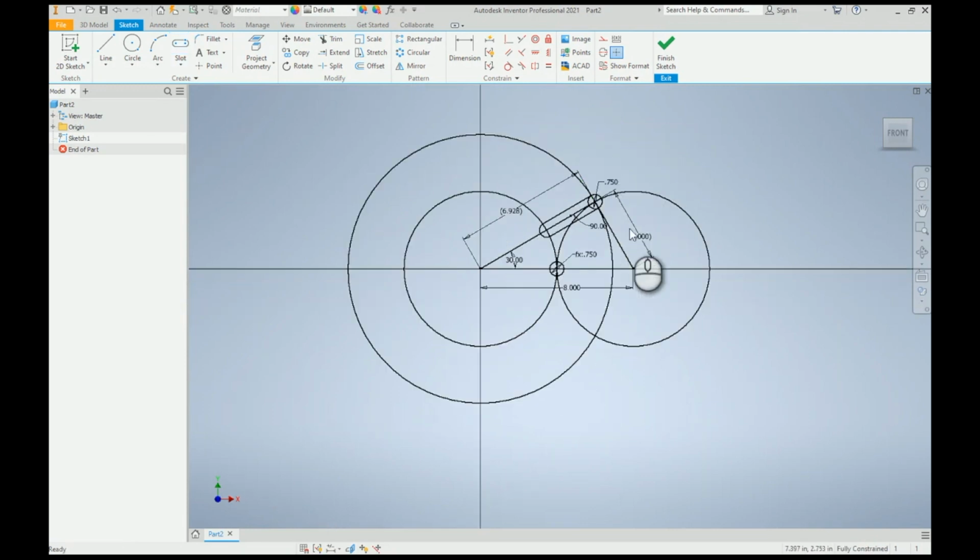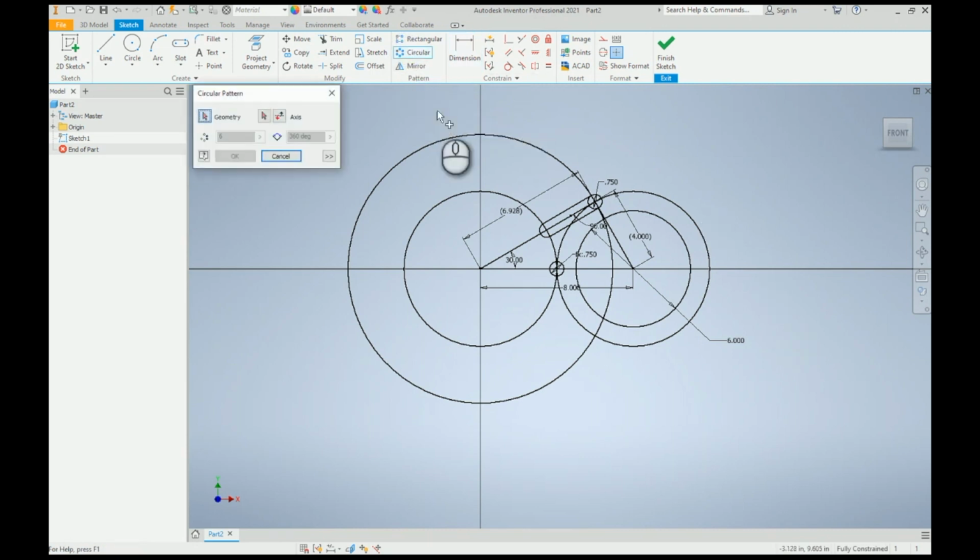A prominent characteristic of the Geneva wheel mechanism is that it stays locked when it is not rotating. This is achieved in different ways, but commonly it is held with a shoulder on the crank wheel. Let's place a circle here, let's dimension it arbitrarily, just proportion. This is the shoulder on the crank wheel, and a mating cut has to be done on the Geneva wheel as many times as it stops.